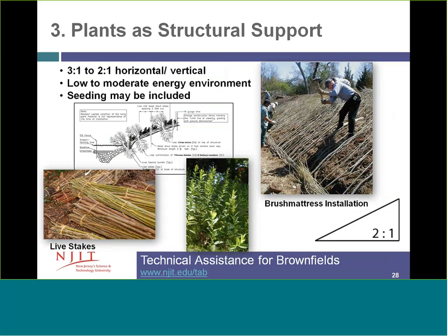The third condition, again, now we're going up in the energy environment as well as the slope condition. This would be on slopes of 2 to 1, not any steeper than that, but in this condition, you can actually consider using plants as structural support. You see on the lower left a photograph of live stakes, which is basically dormant plant material that's cut in the winter and kept chilled until it's put in the ground.